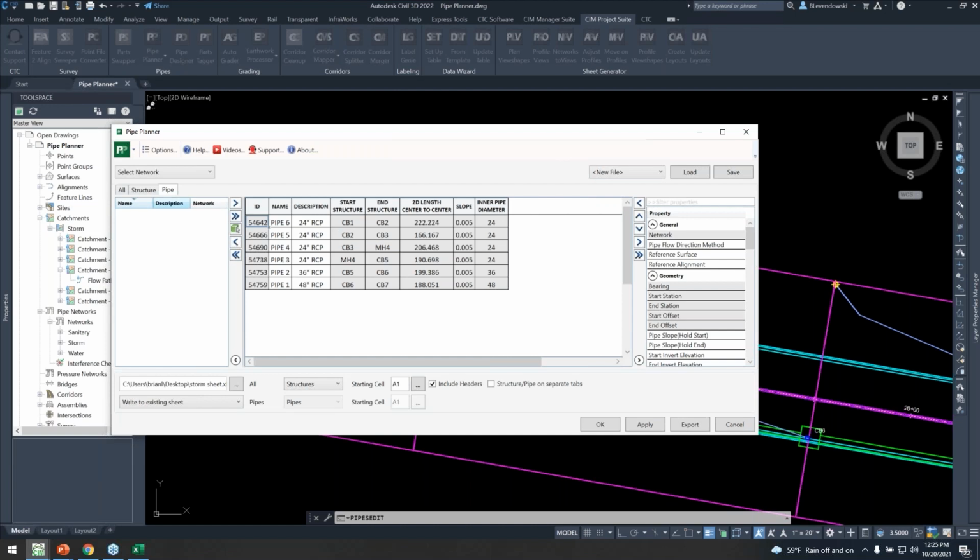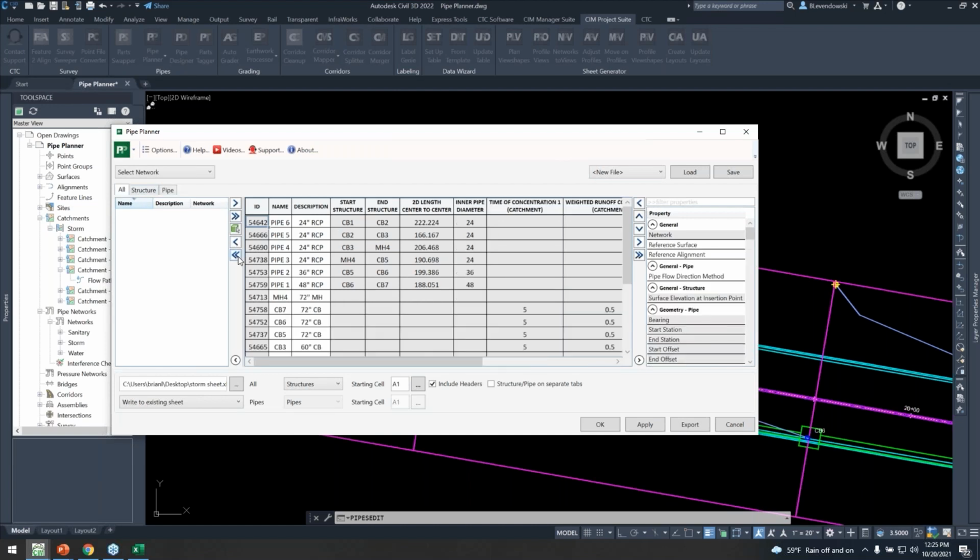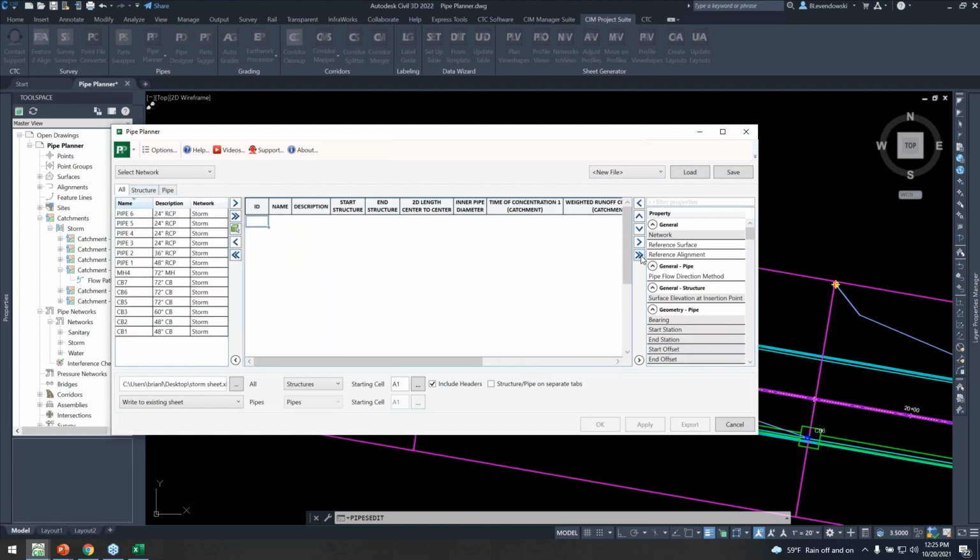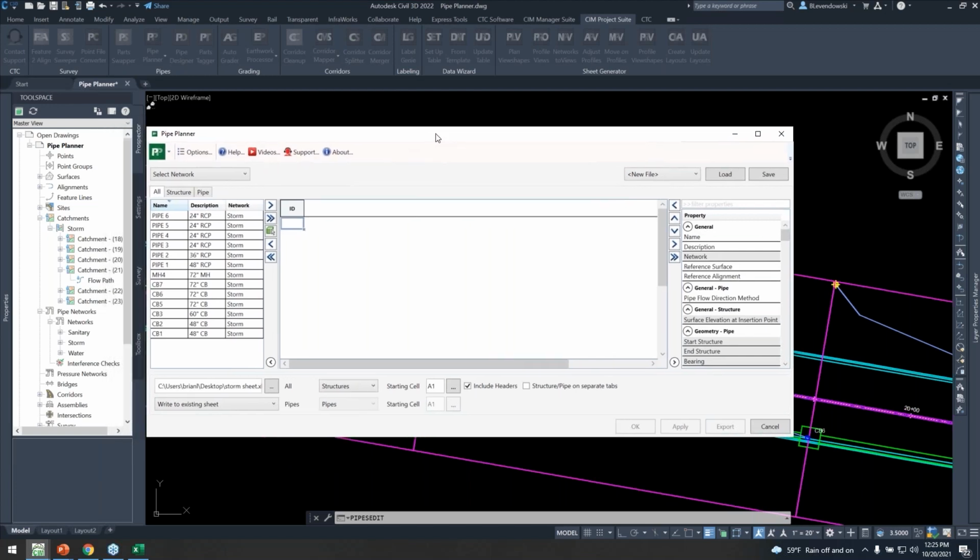And if we clear this out, let's go to the All tab here. Let's say we didn't have any properties or anything loaded. If we click load on this one here, it's going to populate everything. Now, a couple of key things to note. What templates save are, of course, the property information and the order it's saved in, but they also save the part IDs.